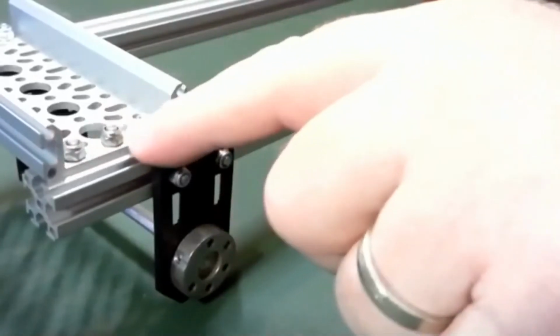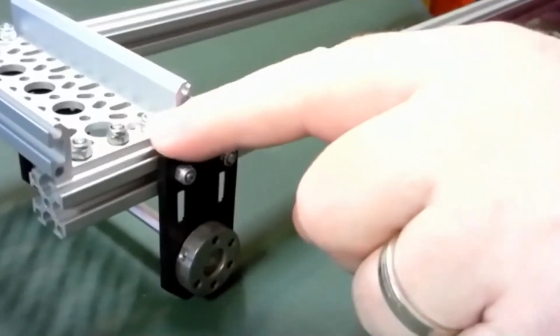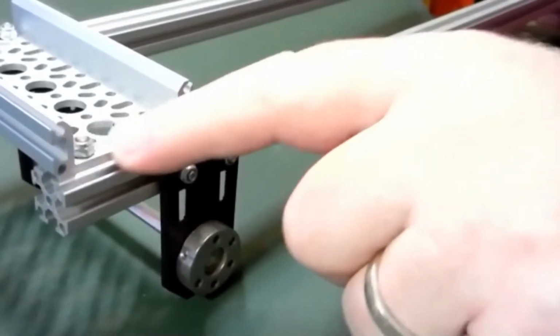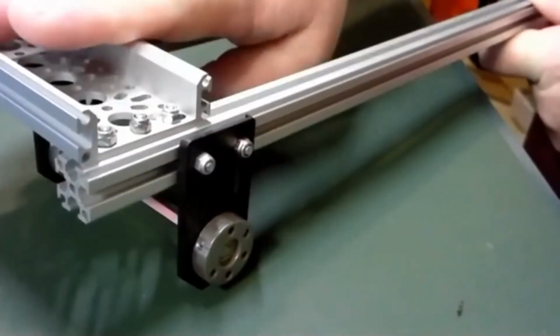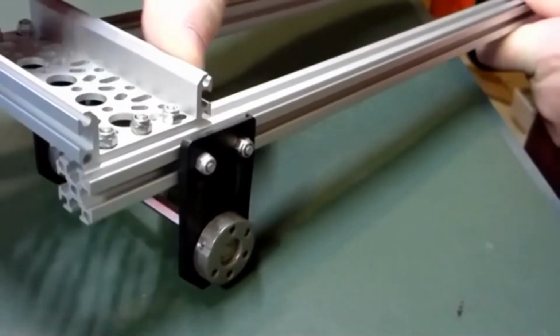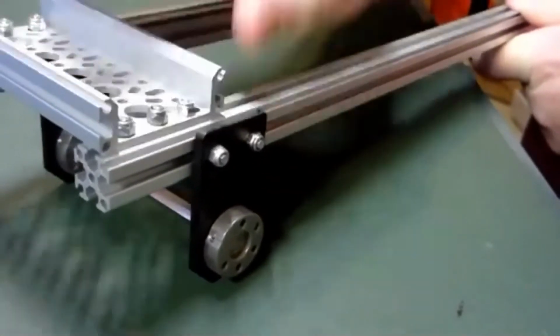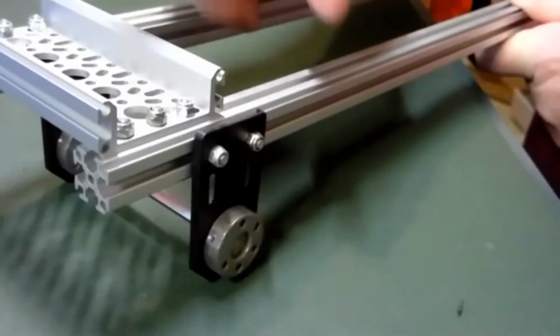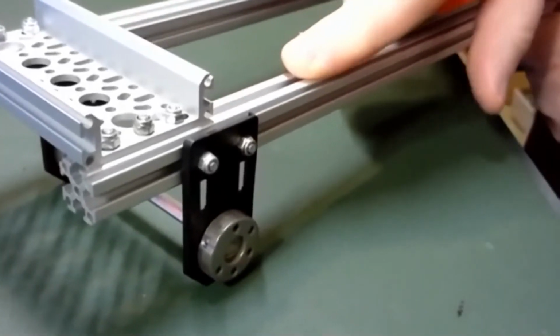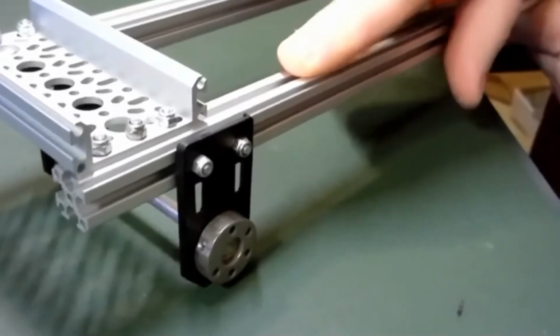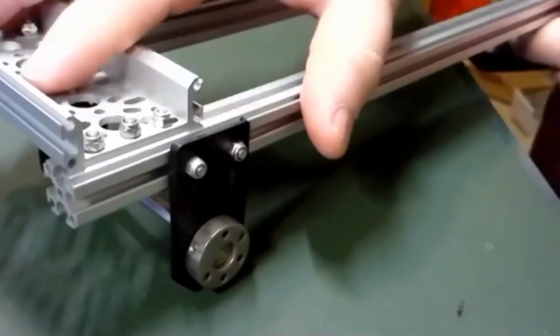So what I'm going to want to try and do is to attach the channel using 3 screws here that are on those end holes of the channel. And what that's going to do is, first of all, attach the channel very nicely to the extrusion. But secondly, it's not going to want to rotate. So I can be reasonably certain that the channel is perpendicular to the extrusion. Now, obviously, it could be fractions of a degree off, and you might still want to use a T-square or something like that. But at least I'll know that it's there.